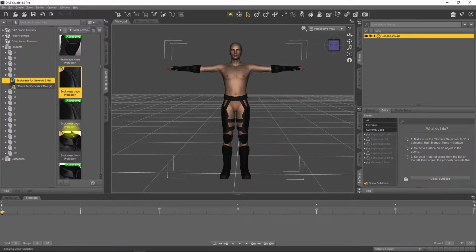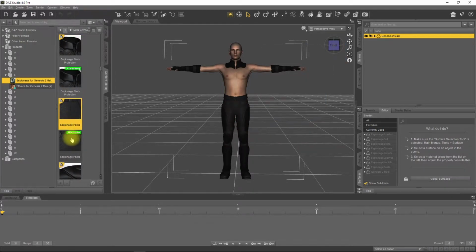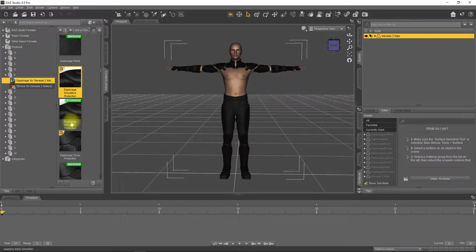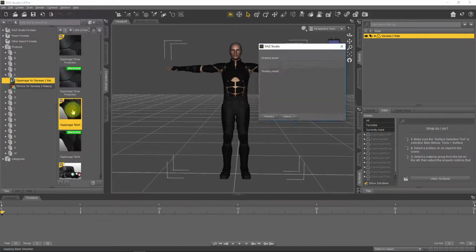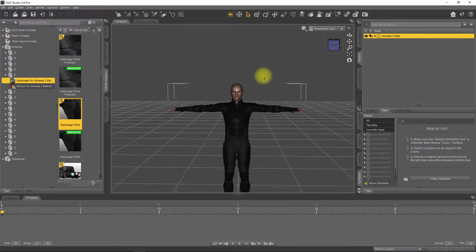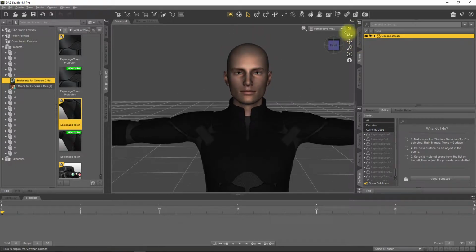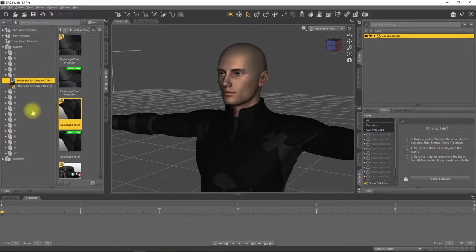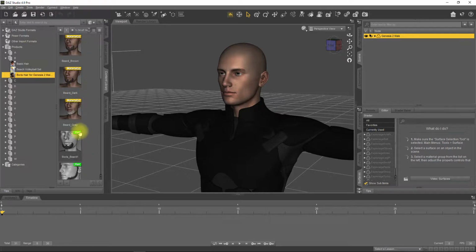And while I'm getting all this set up, the main thing is a lot of the materials, when we export them out of Daz, export as JPEGs, and therefore without transparency, Element 3D does not see the elements the same way, and therefore everything looks very blocky, very chopped up. And I'm going to show you how to use the color range to create a PNG with transparency that can be recognized in Element, and again improve the overall appearance.